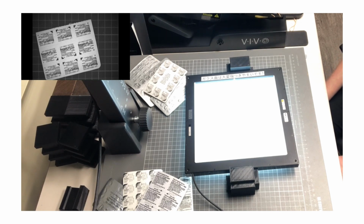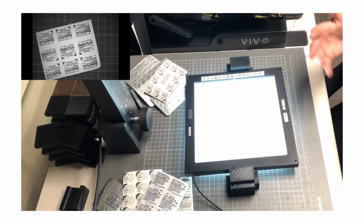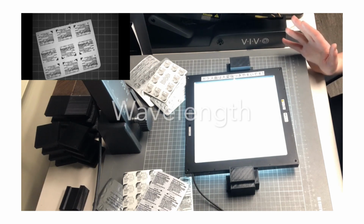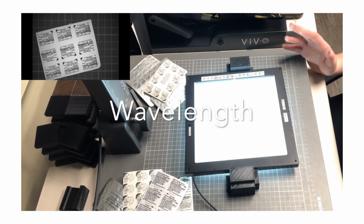So I know that the flat dome light is the light form factor that I want. So I know that I want bright field. I know that I want a flat dome light for this inspection, but now I need to check wavelength. So all of this is white, silver, black, red, green, blue. Probably doesn't matter.